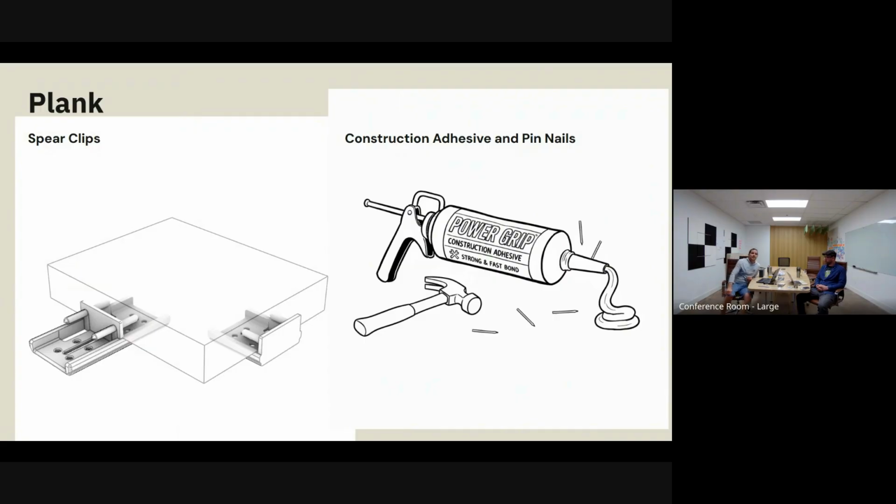But it's nice if you have an uneven wall, so you can throw some furring strips up there to make it level and then use these across. Or you can actually do this to T-grid too, if they don't need plenum access but they have T-grid. You use your T-grid and throw a furring strip up there, and now you have these to go across. So it's very versatile and very simple. The downside is it is one of our more expensive hardwares.